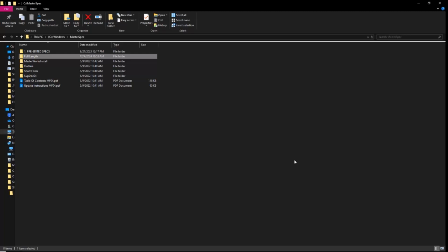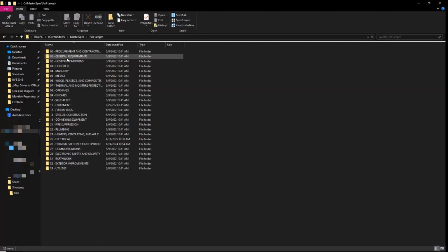By the same token, for the people on YouTube, her and I are familiar with the differences between sheet specs and book specs, but we are also using what are called division numbers. The quick story behind these is that this is the second revision of what these division numbers look like. I believe electrical was 24 for decades, and then around 1992, 1994, somewhere around there, maybe 2004, I don't remember, this new numbering came up, and now electrical is 26. So anything under the 26 header would be electrical.